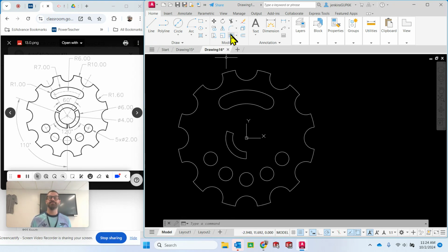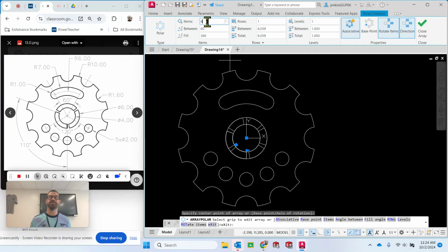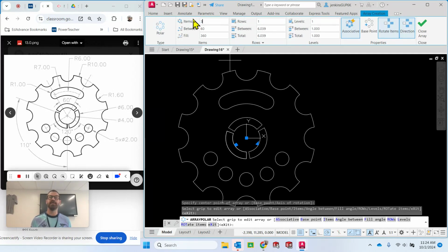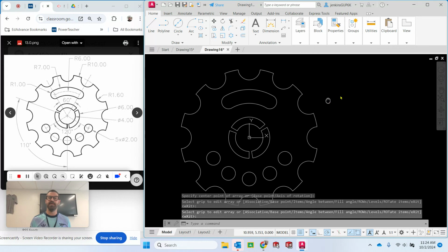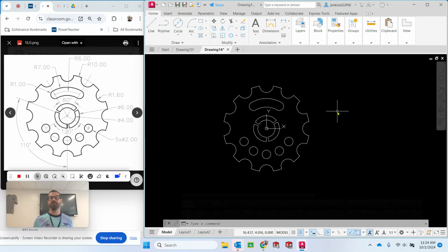So now I'm going to click on this guy and say polar array. And what's my center point? That's my center point. I don't want 6. I want 3. And I do want it to go 360 degrees, all the way around. That looks good. The direction looks fine. Doesn't matter. I don't care about any of this other stuff. I'm going to hit OK. And at that point, everybody, we have our drawing complete.